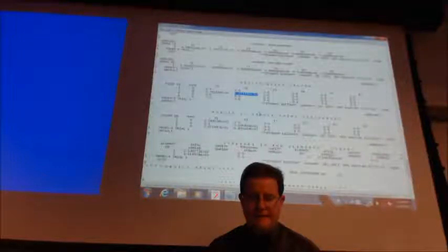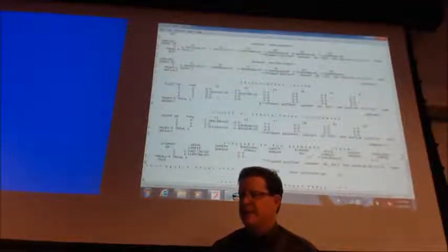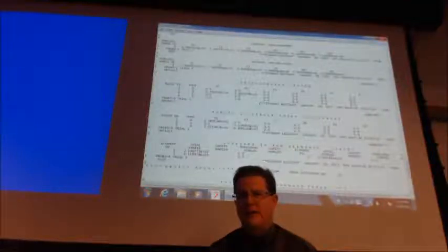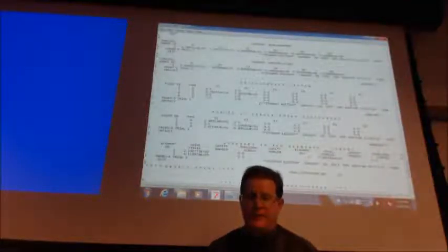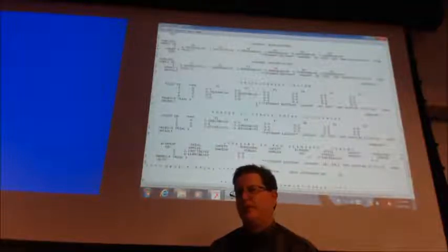218. And they also talked about the forces. Let's see, we got displacement. So there's our minus in the X, plus in the Y. We'll be coming back to this F06 file and looking at it for a lot of our information. Hopefully you're less likely to believe the siren songs of the pretty pictures.